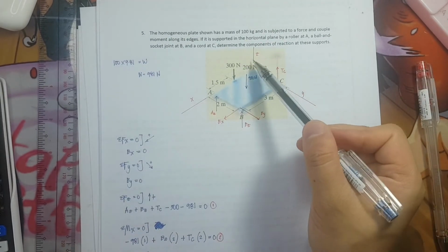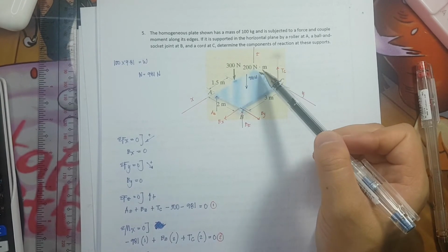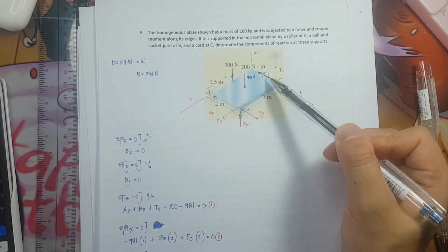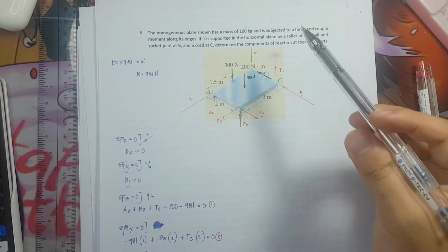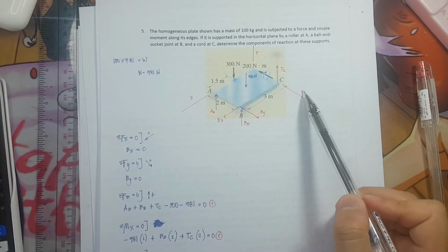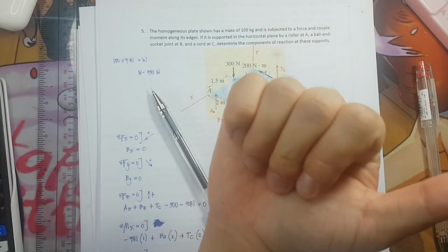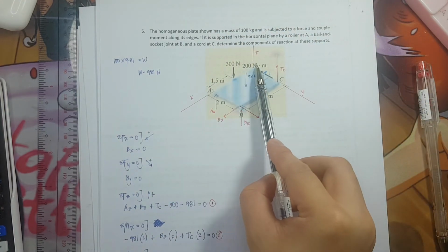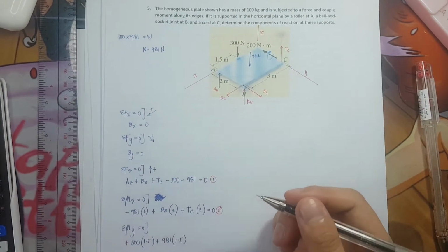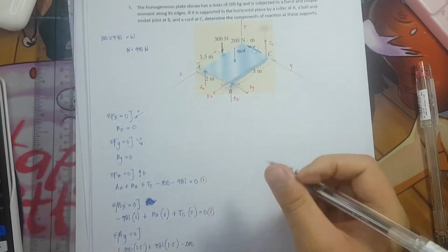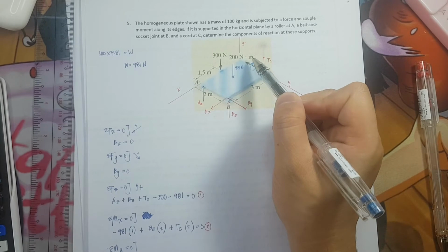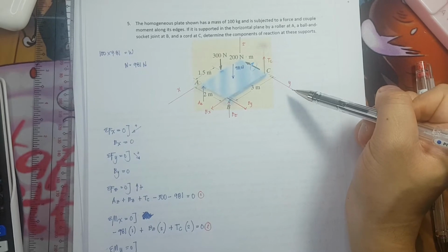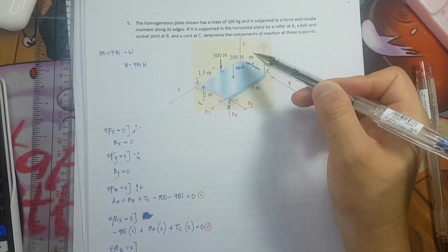By the way, the 200 here should not be cancelled out because that is a moment. That is not a force. If you're going to check the rotation, it is rotating in a clockwise manner with respect to our y-axis, and the counterclockwise manner is our positive direction. Therefore, the 200 Newton meter moment here is negative, so minus 200. I repeat, we should not cancel out the 200 here because that is a moment rotating with respect to the y-axis. Okay, that is a correction. And we do not include a lever arm because that is already a moment.